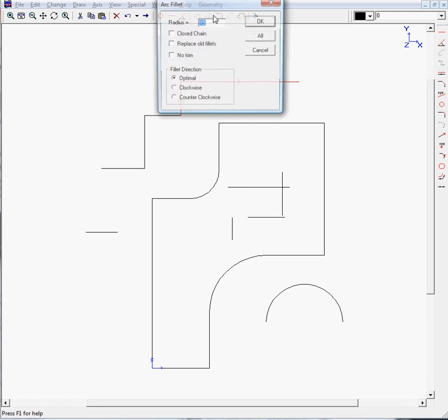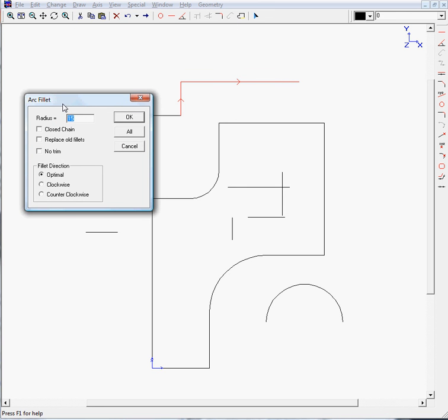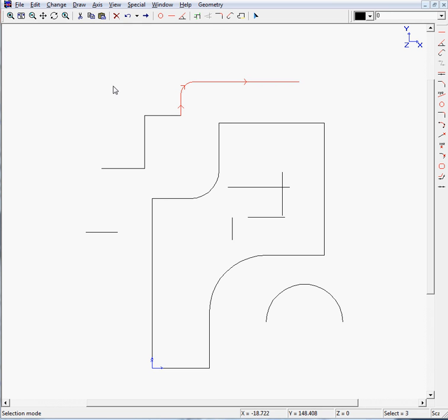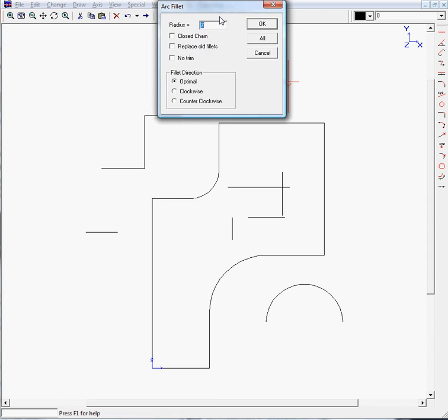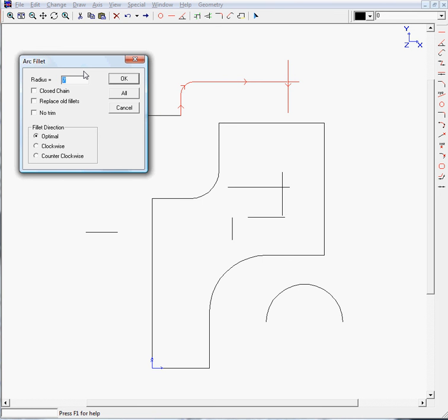If I now fillet this corner with a radius of 7, for example, you would ask, what is my last element in this case? Well, as Tensor helps you a little bit, this would be your last element, this would be your first last element, and this would be your first element. So you can continue on drawing without thinking about your sequence. So you would draw your next line and fillet it, which always takes part on the last 2 elements in your selection, which in this case, this line and this line.